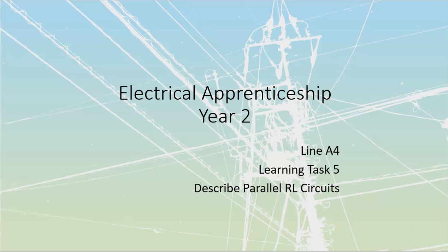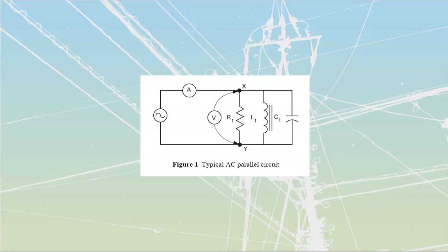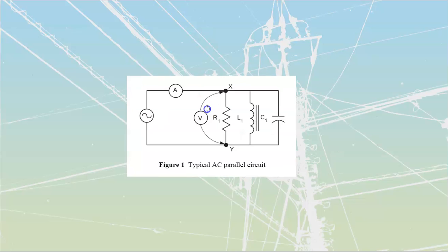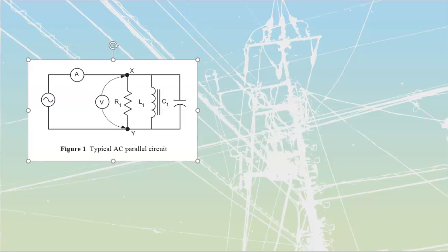Because we are going with a parallel connection, we're also going to utilize a different standardization inside of these circuits. The different thing that we're going to use will be our value of voltage, because we know that ultimately whatever we have for a source voltage gets dropped across this load, across this load, across this load. We no longer sum up all of our voltages. Instead, we've got all of our voltages that are going to be seen across each individual component, each individual branch. As a result, we are now going to use voltage as our reference vector.